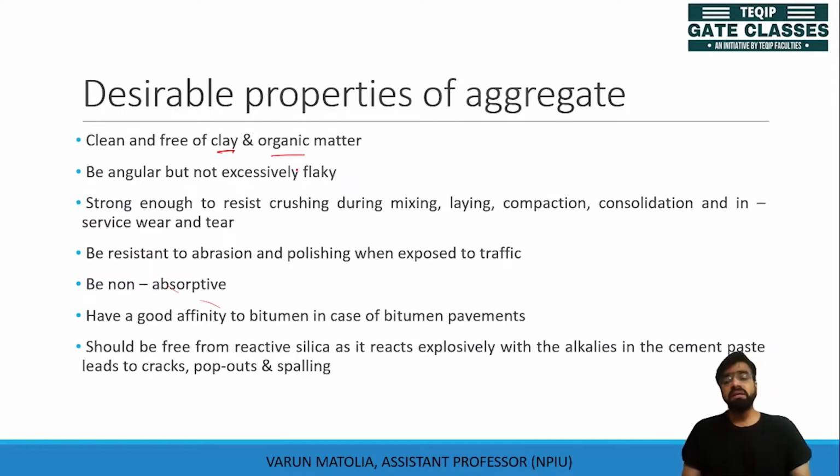Then the aggregate should be angular, because the angular aggregates provide interlocking, which is a desirable property to give strength. But at the same time, they should not be excessively flaky.